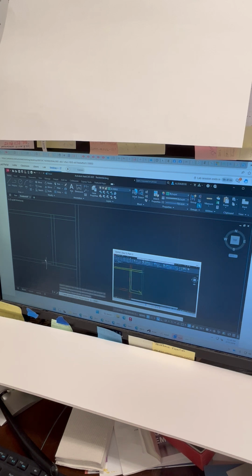All right? So with those elements off stage, you can use your trim command. So just trim this portion up here. And then you can trim these lines here like that. Just like that. And because those were off stage, I don't have to go back and delete anything.